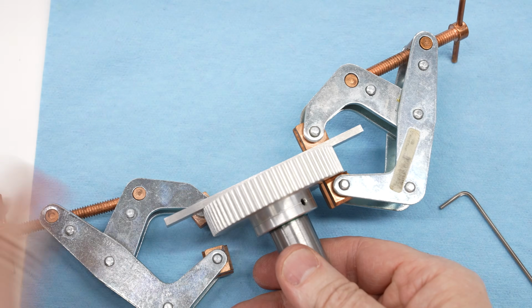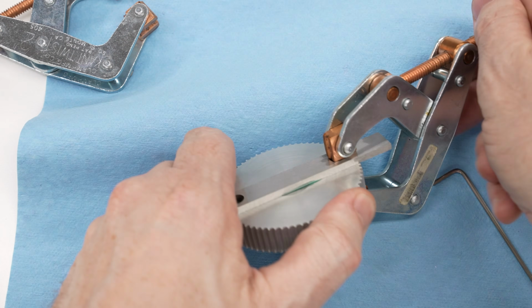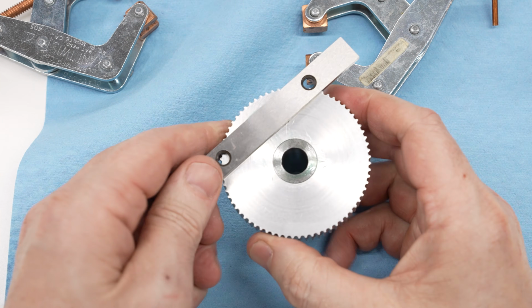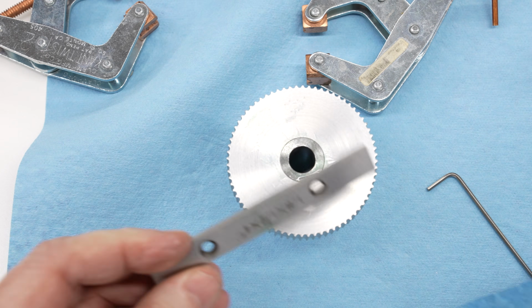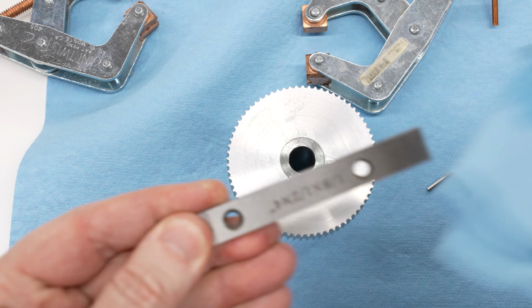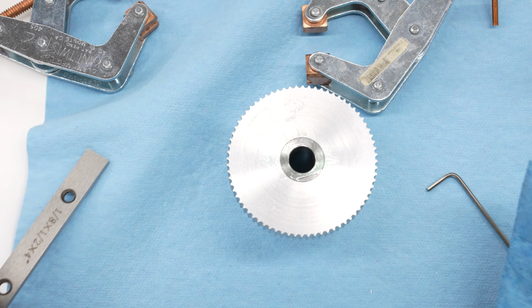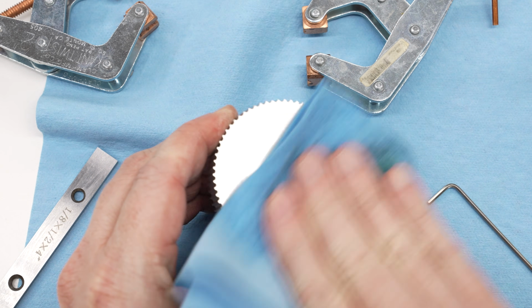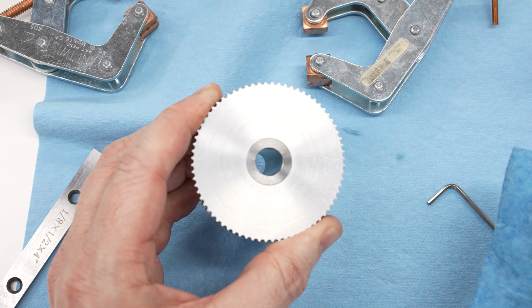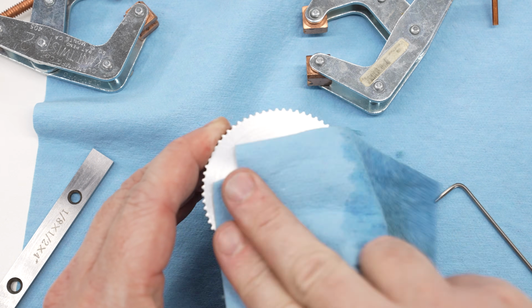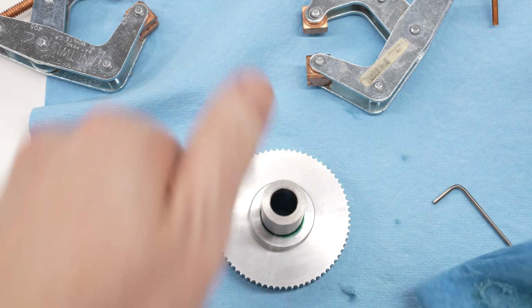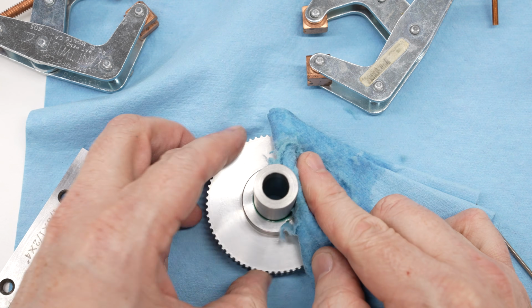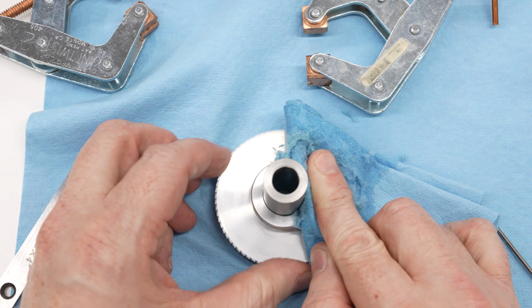Now I could leave the clamps on here, but if I do that, that parallel is going to become a permanent part of this assembly, and I definitely don't want that. So I'll take it off now that the set screws are locked to hold it together, and I'll wipe off the excess. Now this rag still has some alcohol on it from the cleanup, and so it makes short work of cleaning up the extra retaining compound. In fact, you won't even be able to tell the retaining compound is in there once this is all cleaned up.